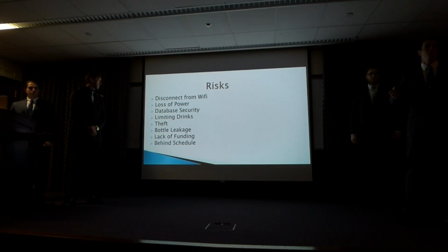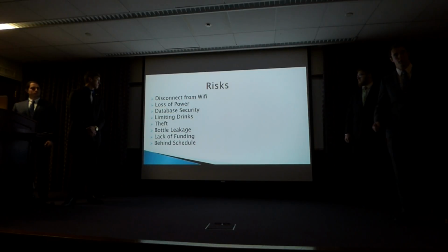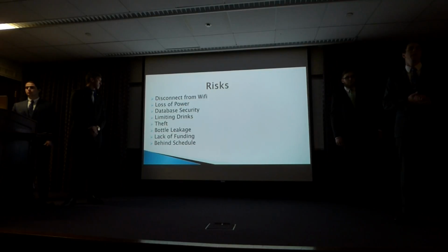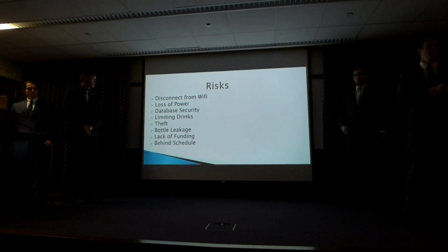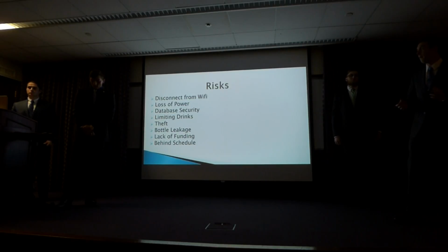Next we thought about, well, what happens when we lose power? Since we're using normally closed solenoid valves, they're only open when they have power applied across them. So in the event of a loss of power, they will all remain closed, preventing the leakage of product.